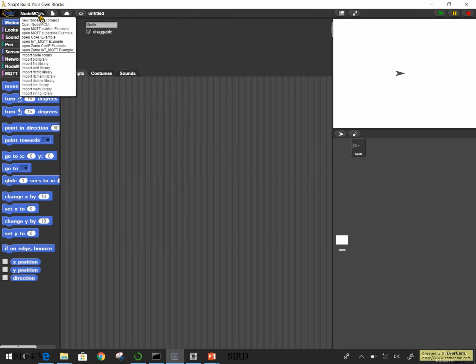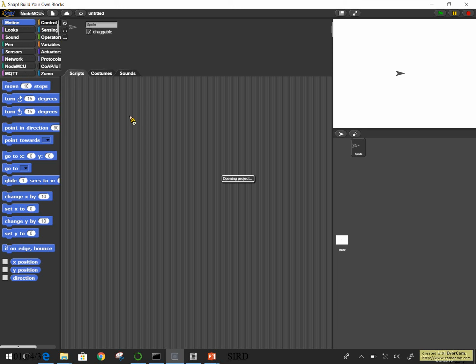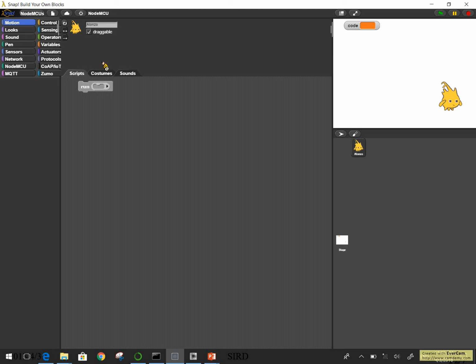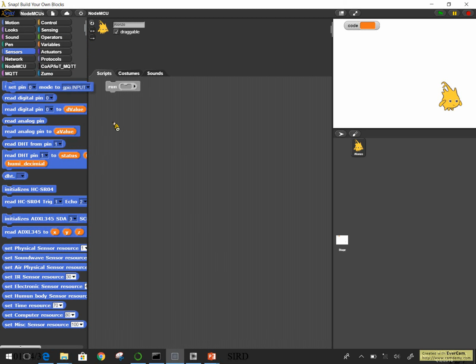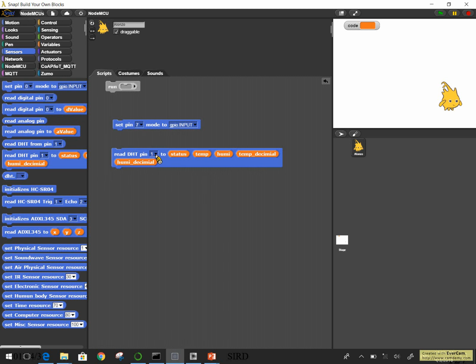First, we create a new object. Okay, so just like what you do with the sensor, right? Remember last week we said that for the sensor you set the pin, maybe 7 in our case. So you have pin 7 as input, and also you want to read the temperature, right? So you put 7 here. This is just for a safety check, because you won't know, the previous one may have been set as output. So for your safety, okay.